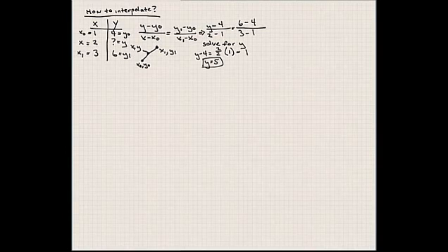And keep in mind, when we make these assumptions of interpolating, we're assuming that the points are close enough together, so the distance between x naught and x1 are close enough together that we assume that it's a straight line. Some of these thermodynamic relationships, though, are not always a straight line, but we're assuming that they are a straight line, and that interpolation is going to give us a close enough value to the real value.